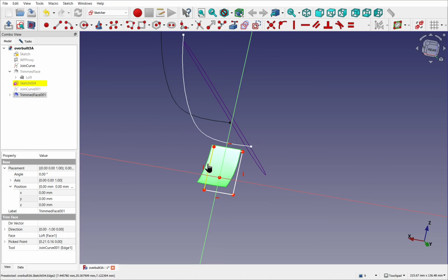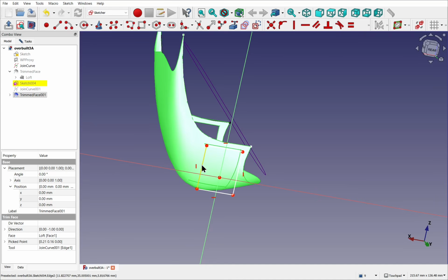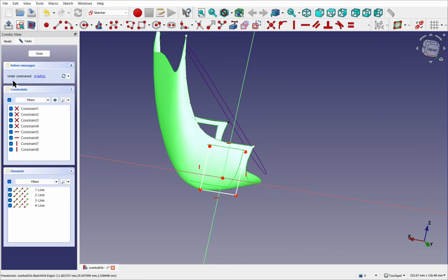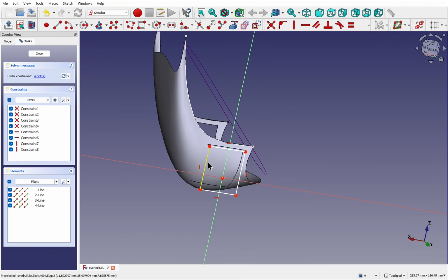You can see that's refreshing as I pull that across. The reason why that refreshed straight away is that on the task button here, if I drop that down, I've got the auto update checked. So I'm going to uncheck that. That's the default state where it hasn't been checked. That means if I move this now, you can see it's not auto updating.